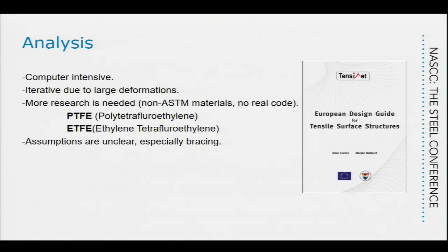And one of the biggest problems that's happening in the industry right now is, does the membrane brace the steel structure? You know, we understand that if we put a steel deck or if we put a composite deck, we can fairly assume that deck, if we weld it correctly, is going to brace our structure. But if you have a membrane, the question is, does it?